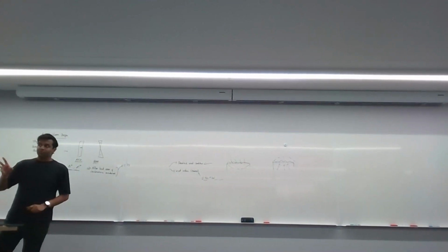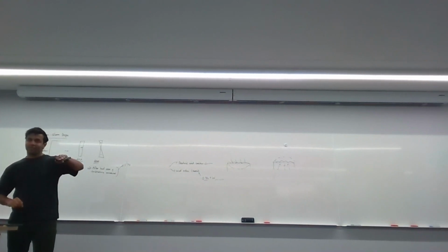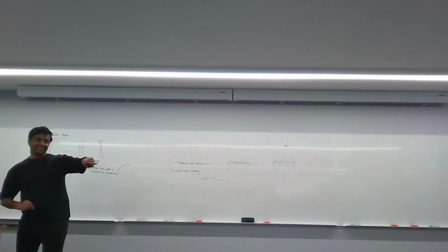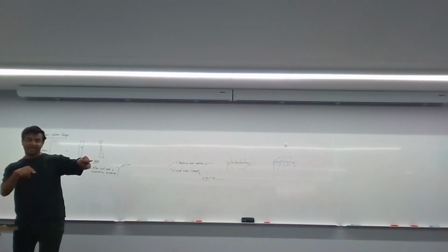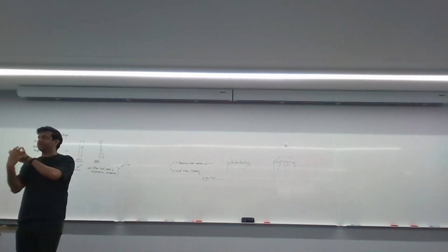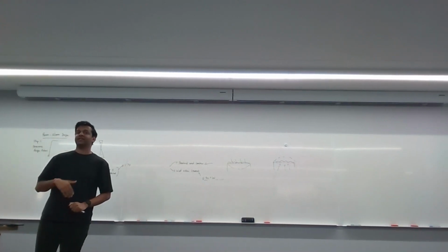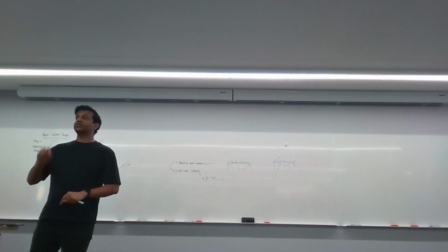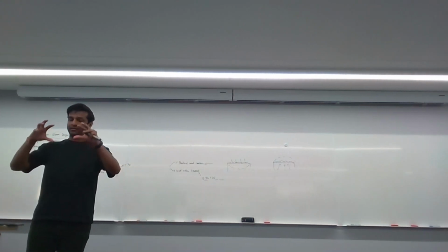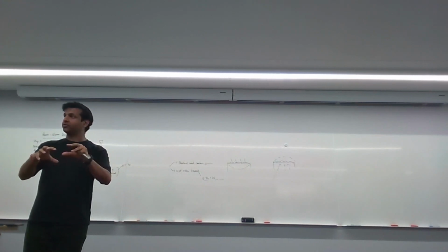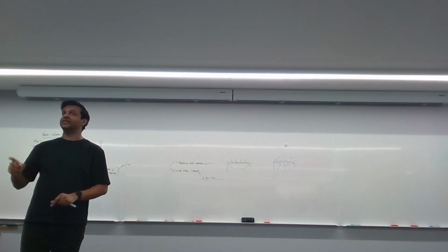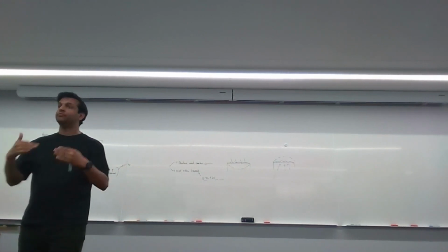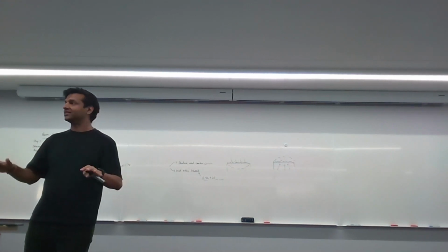What you don't do is go, oh, from load combination A, I'm going to pick N star from here, and then from B, I'll pick M star from there, and then put them together. You can't do that, okay? Because it's too unfair to the system. If you're saying that N star and M star are the values that I'm going to use to design my building, you must remember that they both must be coming from the same load combination. If not, it's not realistic, right?